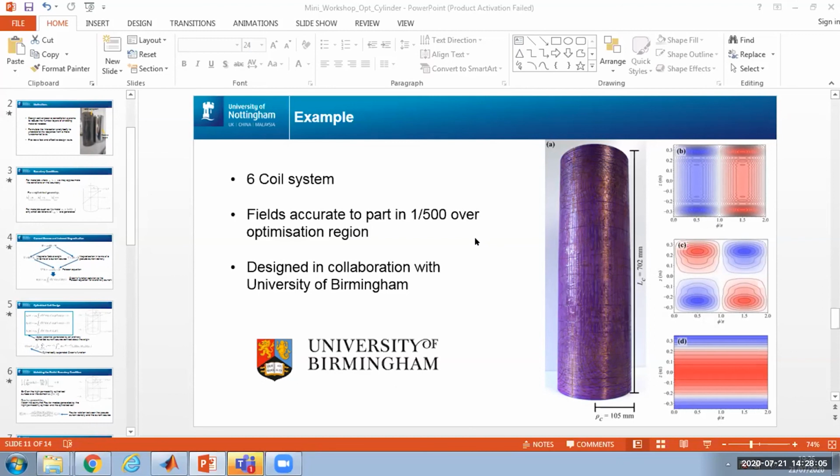With all of the coils with the PCBs, every PCB is actually a biplanar system where you've got a top side of the coil and a bottom side of the coil, and then you have vias that go through the PCB to facilitate the joining of contours up and down the cylinder. Every time you would like to join a contour, you move to the other layer, apply a joiner, then come back up through the PCB and attach onto another contour and continue on your path.